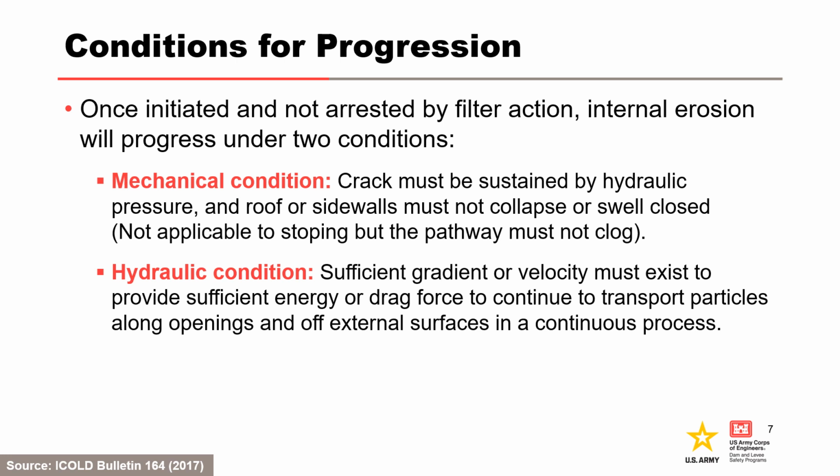For the hydraulic condition, sufficient gradient or velocity must exist to provide sufficient energy or drag force to continue to transport particles along openings and off external surfaces in a continuous process.